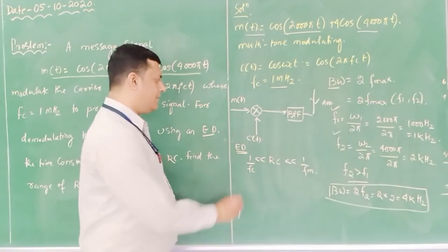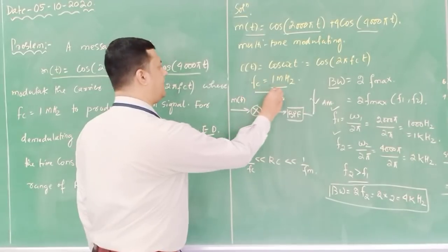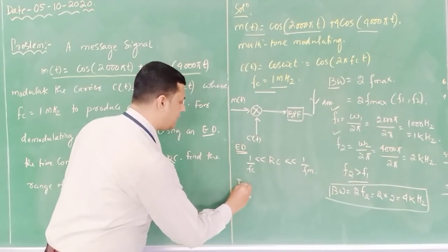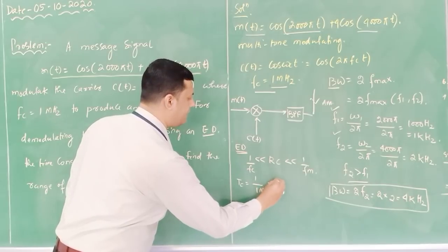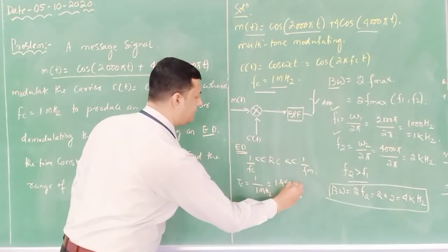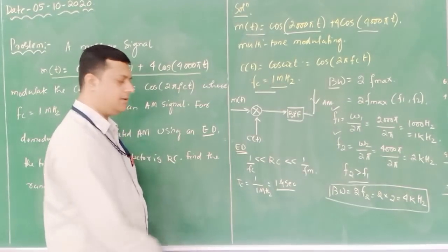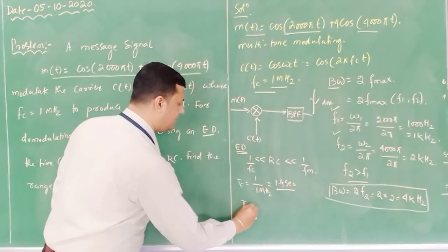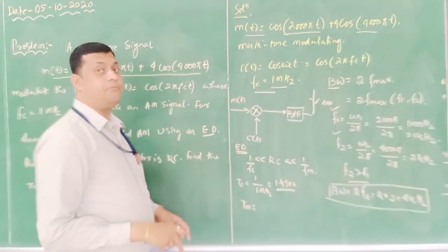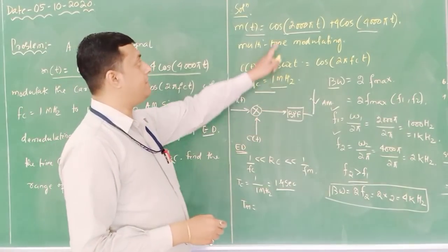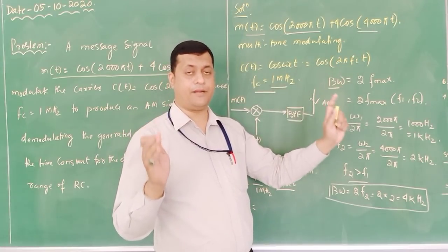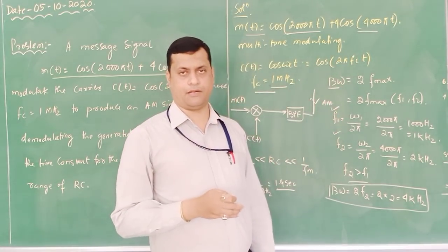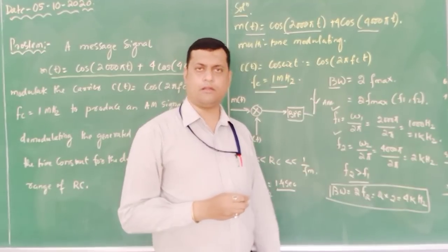Okay. Now what is the carrier frequency? Carrier frequency is this. So fc is equal to 1 megahertz. So again here I will say it is 1 microsecond. Then similarly, what is Tm? Now this Tm plays a vital role. Here we are going to transmit two different modulating signals, but your bandwidth depends upon the higher modulating signal frequency that we have identified, 2f2.